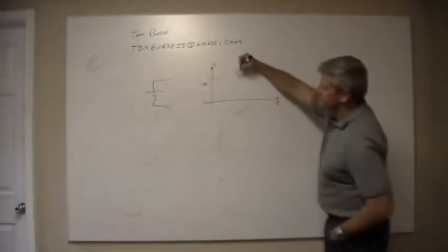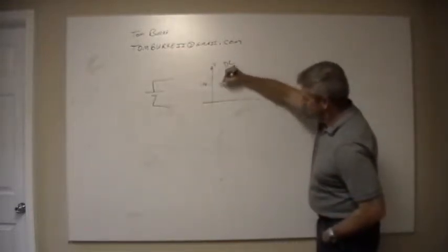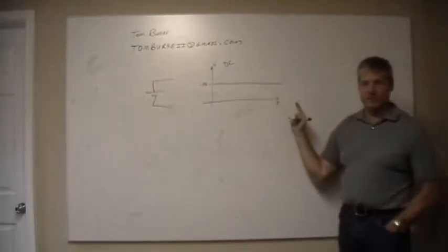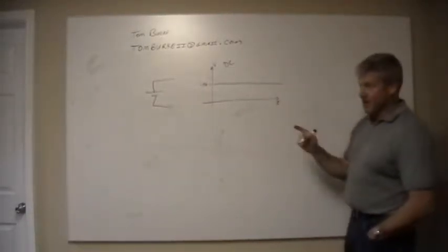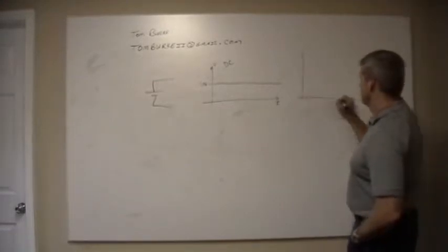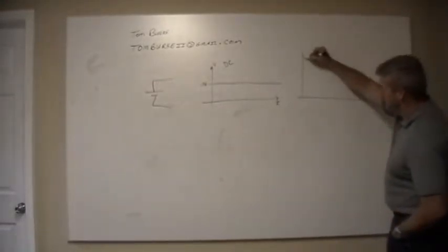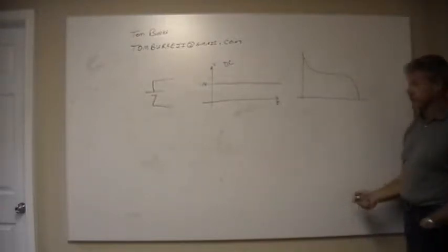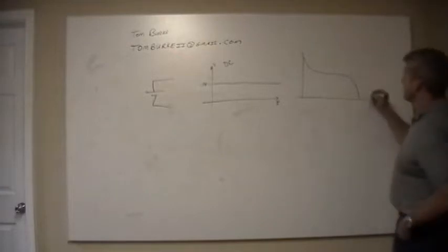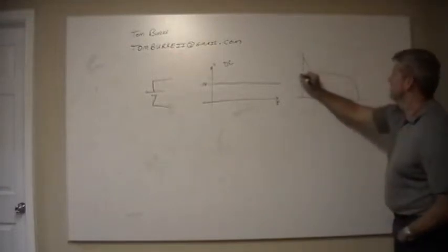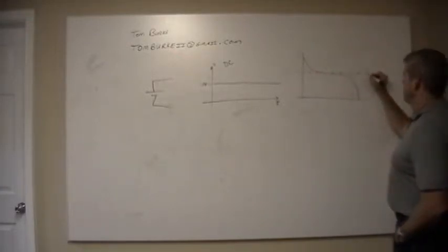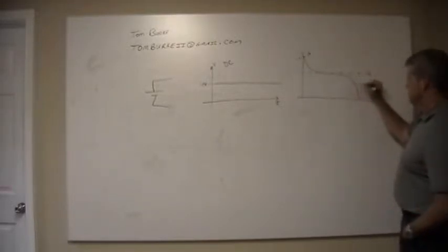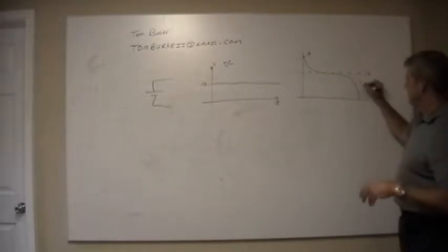1.5 volts. So a DC circuit, it doesn't matter how long I go, it's going to stay at 1.5 volts. What you'll see with an actual battery is the voltage over time does this. So if I talk about a car battery, which is a 12 volt battery, this is your nominal 12, a full charge is about 14, and then it's considered dead around 9 to 10 volts.